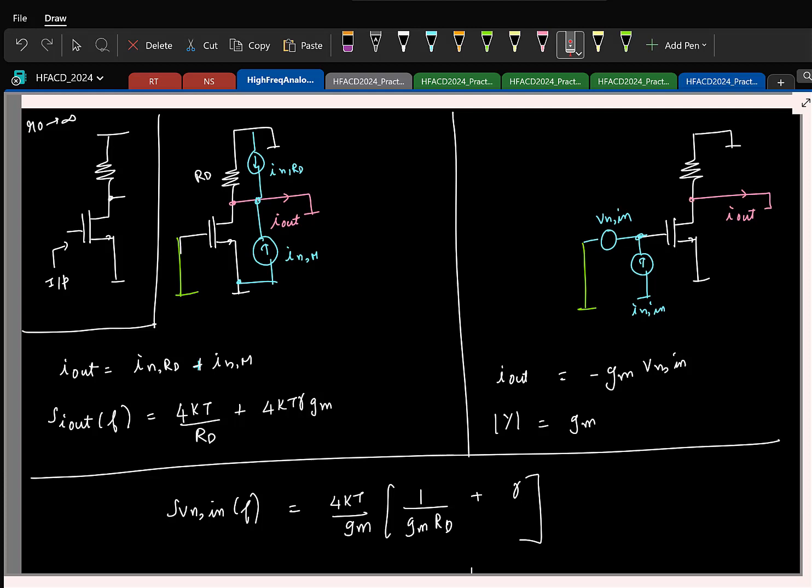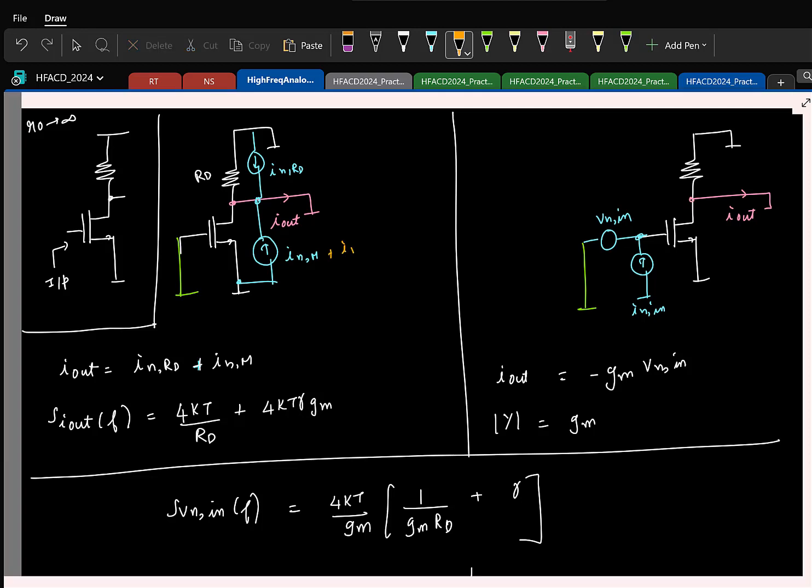So first of all, this noise voltage calculation, is it okay? Is it clear? Yeah, flicker noise. If flicker noise is also there, you can just add it along with it. So basically, whatever we do for the thermal noise, the same thing will happen for flicker noise. That is why we are not considering the noises of MOSFETs separately. The idea is, we want to model this network by a noiseless network.